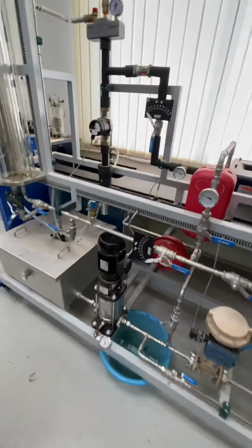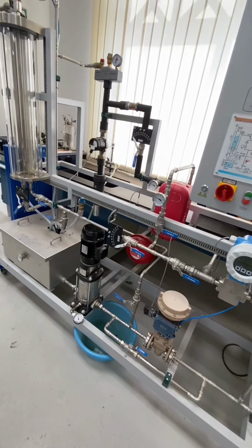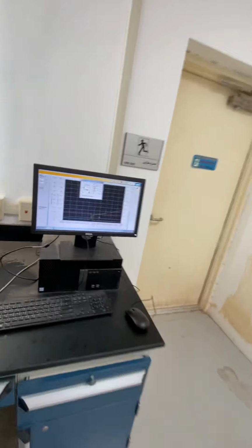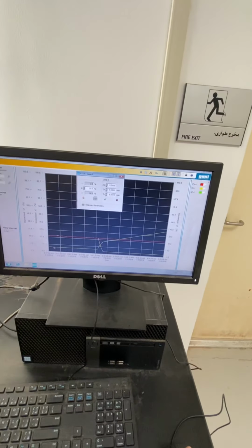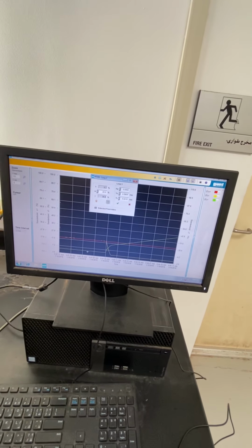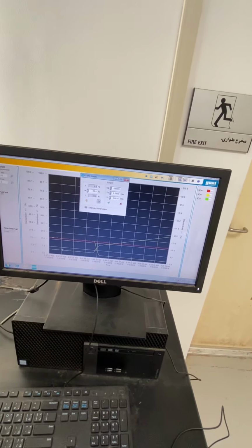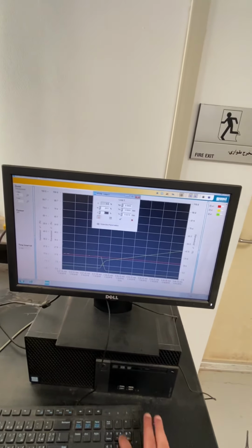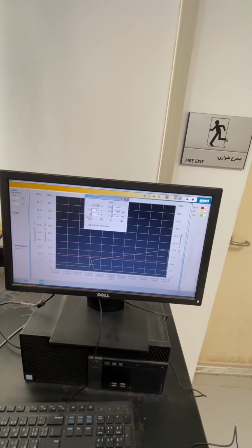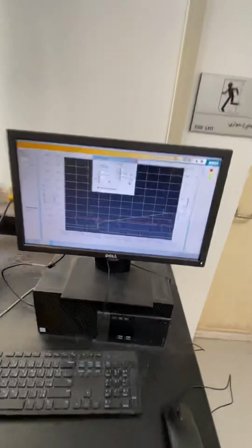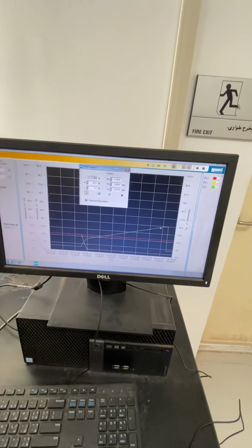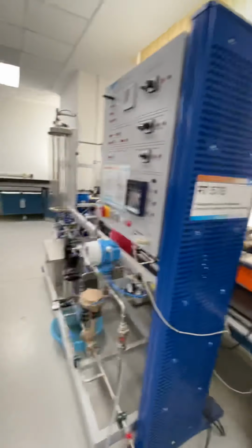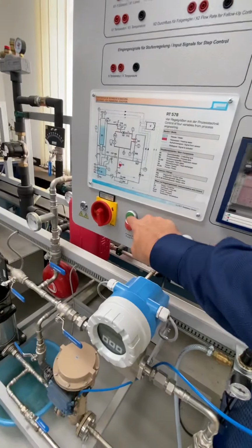But let's say we have some failure in the pump due to which the pump has tripped. In this situation, guys, let's go back and remember the last process value before the pump was switched off. It was somewhere around 7%. We have to switch to the manual mode and write 7%, like so. Because, as we have seen, if we switch on the pump while the output signal is very high, we will see a huge increment in liquid level inside the tank. So we'll switch on the pump again.